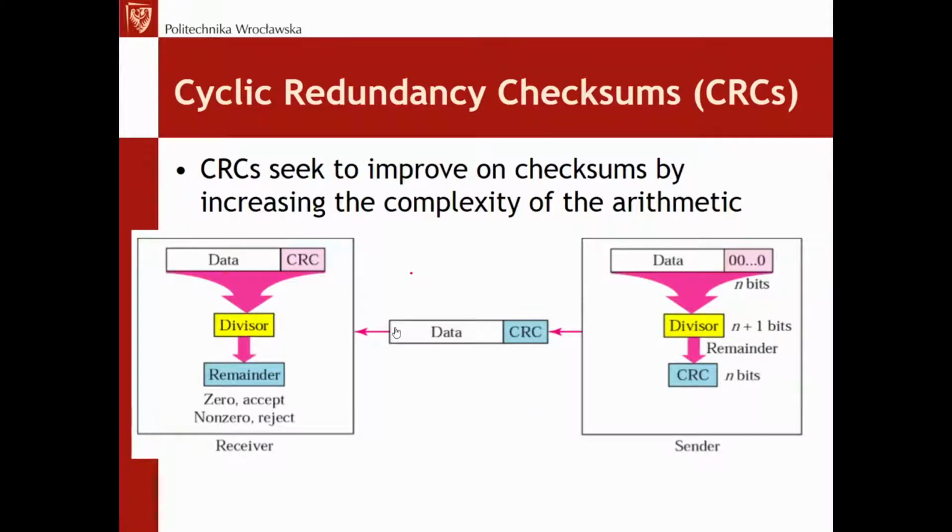That's also the reason why parity is used quite seldom today, only in some hardware accelerated parity checkers, like the UART blocks in microcontrollers. They have the hardware parity, so then we can use the parity. But when we don't have the hardware parity accelerator, which is usually the case, then calculating parity manually makes no sense today, and checksums are used instead.